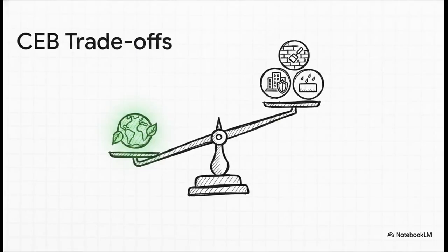However, as analysts, you've got to weigh this massive carbon win against real-world trade-offs. For instance, CEB needs frequent re-rendering in humid climates, roughly every 10 years, and you absolutely must verify structural and moisture resistance. But on the flip side, it strongly supports EDGE and LEED green building material credits. It's all about balancing these factors holistically.